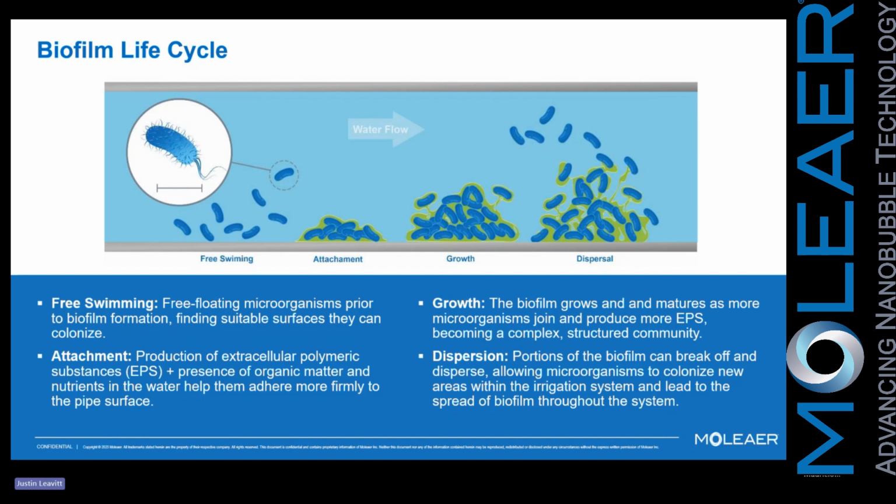And this highlights one of the key problems with biofilm: you can't just manage it a little bit. You really have to manage it from the tank all the way down to that last stripper, because in that dispersal stage, if you have hot spots of biofilm in a single area, it can very easily spread into other areas. And what we end up finding ourselves doing is playing a little bit of cat and mouse if we're just chasing hot spots and not looking at a complex, holistic, preventative, and curative program.